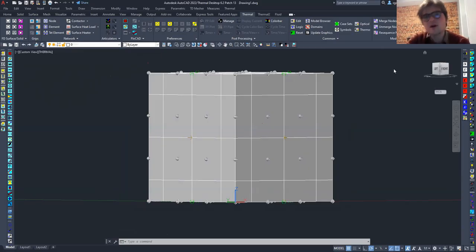So the thing I want to bring up, and this is something I actually more recently learned, is that it's best to subdivide your radiation environments. Out here, you're going to have the sun and the earth, and all this solar radiation coming in. But the inside of this hollow cube sees none of that.